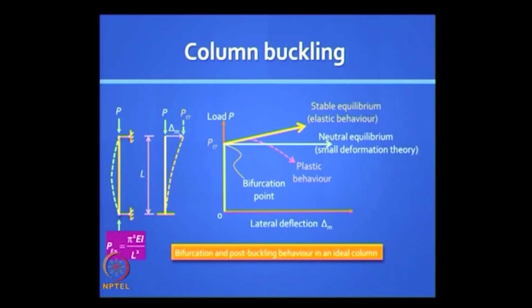You are familiar with this, right? Look at that equation. EI is in the numerator, which means if you had a member with a large flexural rigidity, the buckling load will be much higher, and in the denominator, L is coming into the picture. So if the member is long, then its buckling load is going to be much less. Okay, so these are intuitively obvious, and you can prove for a cantilever it is 1/4 this value. You know this. For a cantilever, it is obviously less stiff than a simply supported case, so it turns out the buckling load is 1/4.